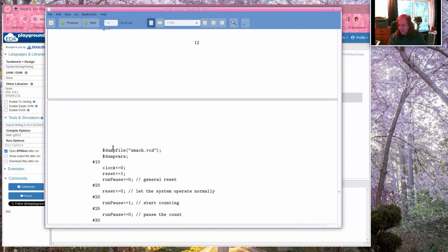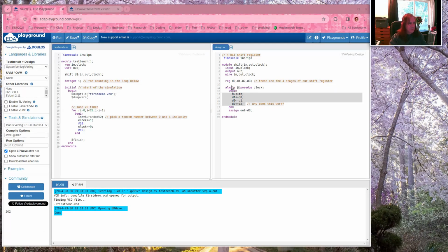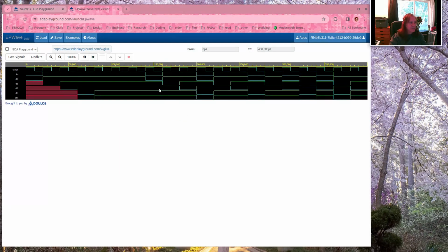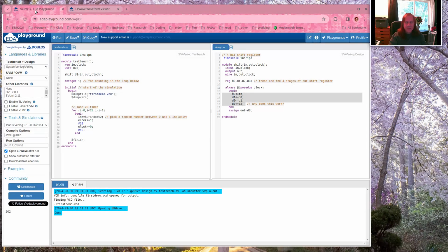Alright, last thing I want to talk about is FPGAs. So we're writing Verilog code, we're writing something to drive it using Verilog, and then we're running it through this simulation tool that shows us what it would do if we actually ran this circuitry, and it shows us timing diagrams. But most software that deals with Verilog also has the ability to take the resulting compiled description of our circuit and use that to program something called an FPGA, a field programmable gate array.